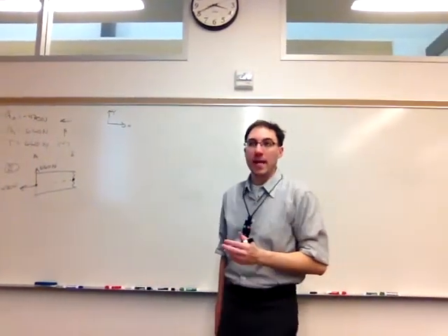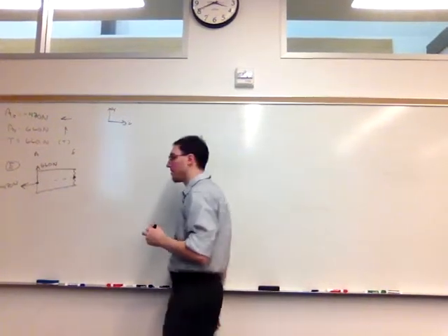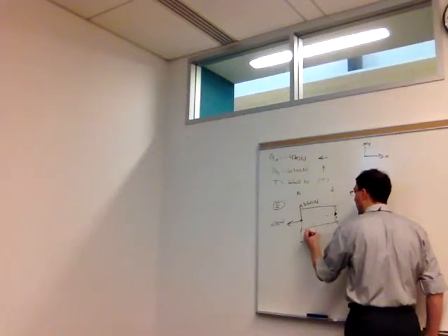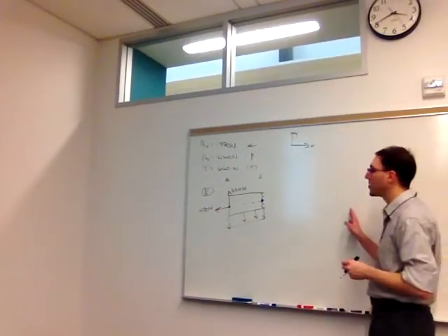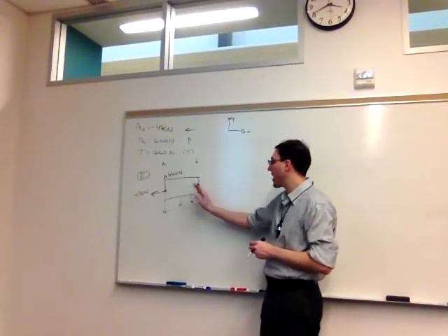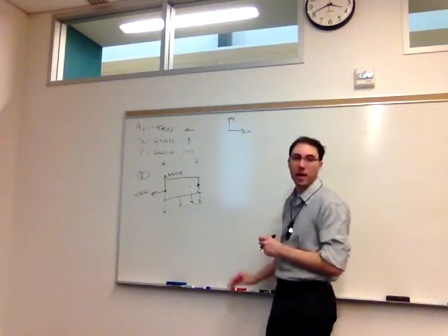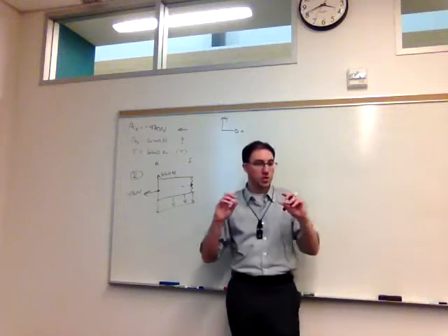And also acting from A to E, the distributed load, only that much of it that touches from A to E. So this piece of the beam can only see that segment of the distributed load. The rest of it is reflected in the value we found for the pin at A, but in this picture it only knows that it goes up to here. It doesn't know what's going on in the rest of it. We do need to keep this, or it is a distributed load.